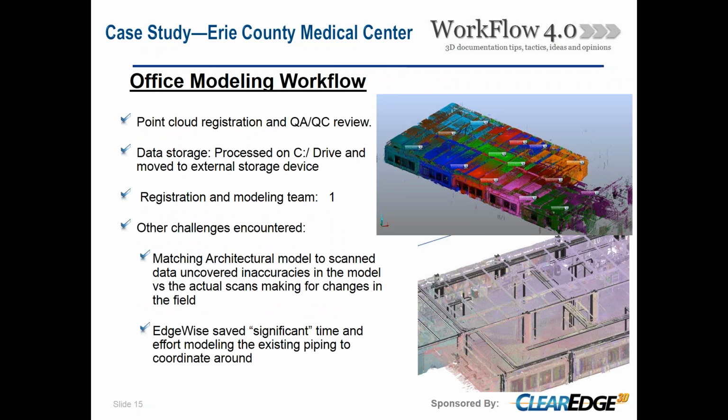As far as the modeling workflow goes, we would use Scene to register the point clouds. Basically, check the QA/QC to see if they lined up properly, how they came in, and what the data looked like. Everything was stored on our C drive. We actually, at one point, were trying to store them on the network, and I got a nice call saying, our network has no space left. Can you please remove all your scans?